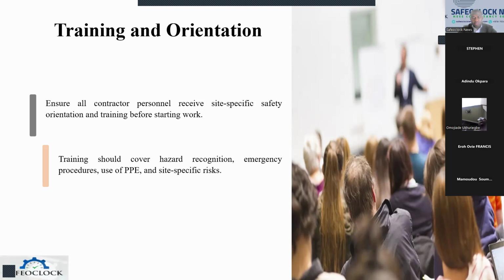So we need to give them training and orientation with respect to that specific aspect of their job. The training should cover the specific or general hazards recognized within that project site. They also need to be aware of the emergency procedures, the use of PPE, and specific risks as they relate to the activity and to that project site.